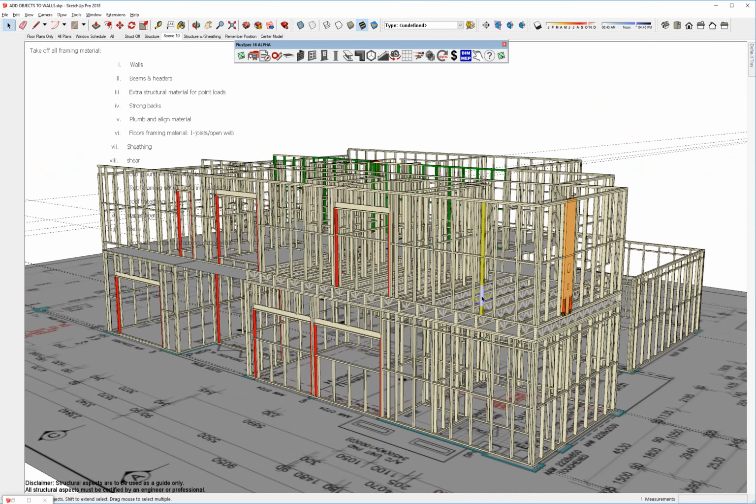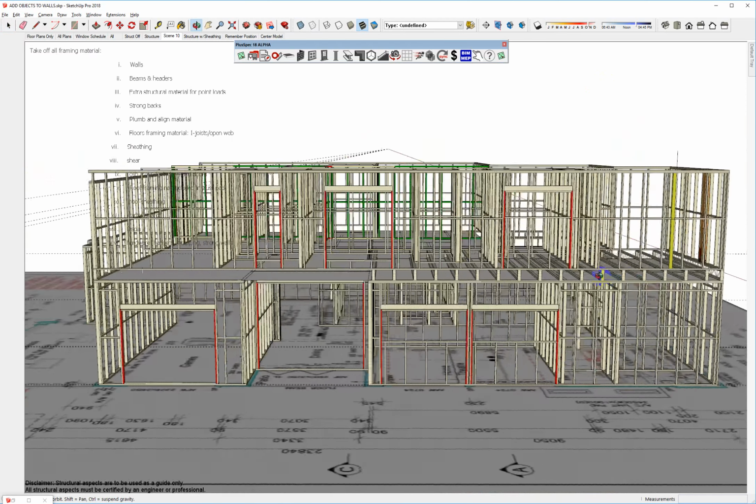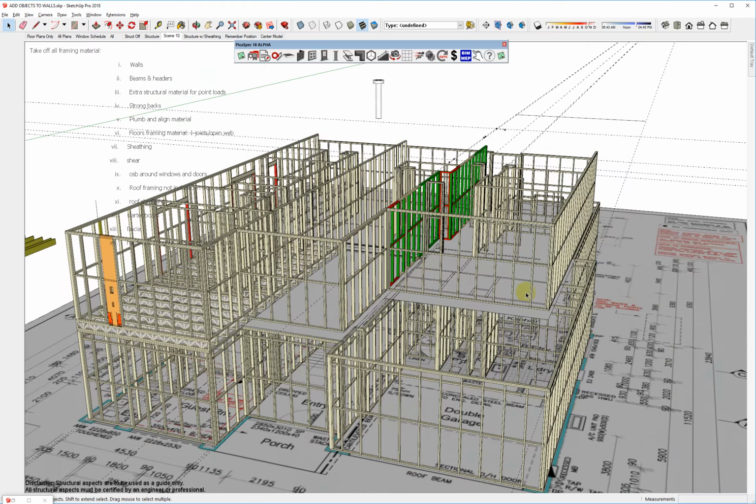So as a builder, I know that some of the biggest problems I come across was point loads, being in between joists, and then buckling the bottom plate and so on. I can't see any reason for it to happen anymore. I believe that this is the best way to virtually design and build a project, and to iron out the bumps before you start, and it doesn't take long.